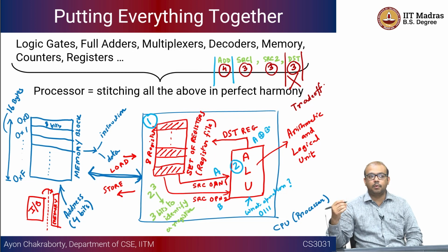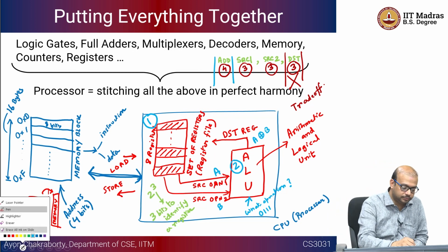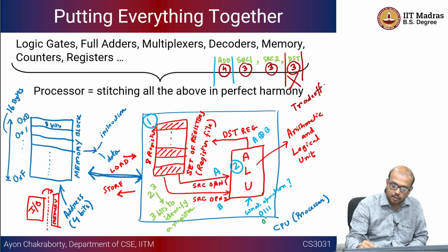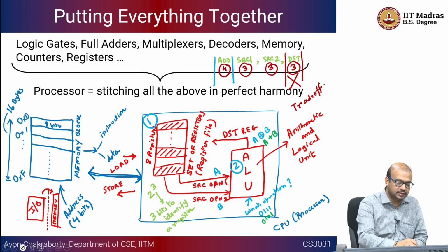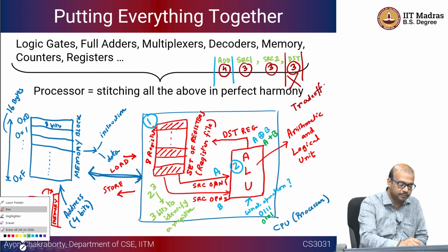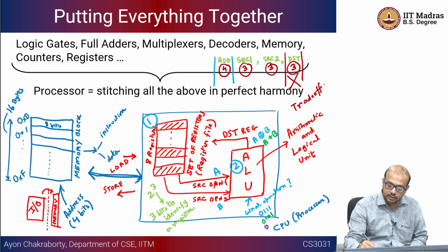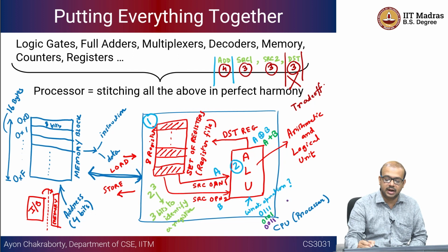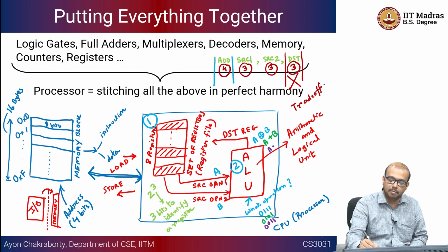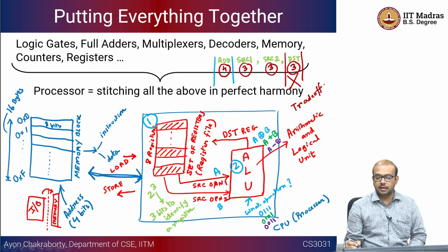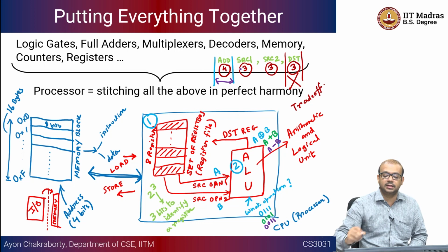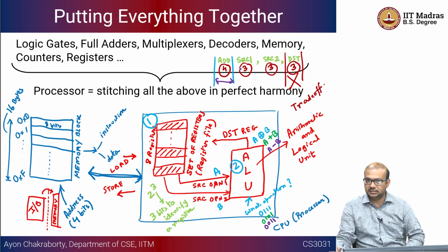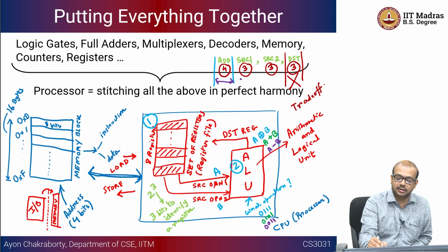Whenever it sees 0101, which is let us say add, it is going to compute A plus B. Whenever it sees, let us say, 3, which could be 0011, and could stand for subtraction, it will do A minus B. So, the first 4 bits here denote the operation that is going to be executed on the processor, and the rest we are going to define.